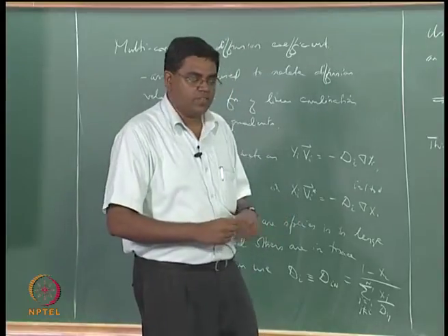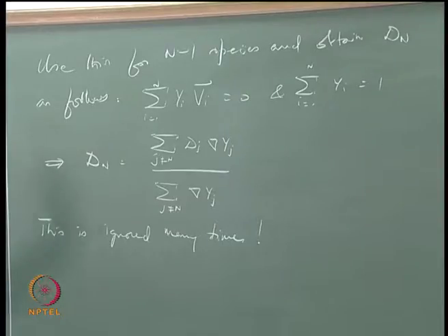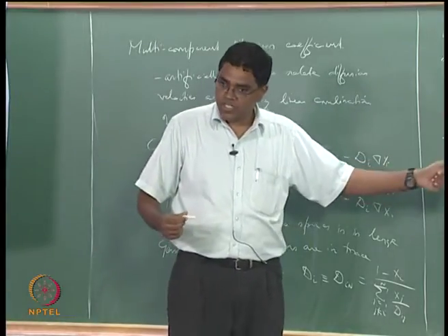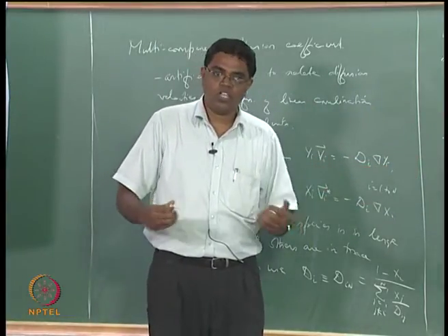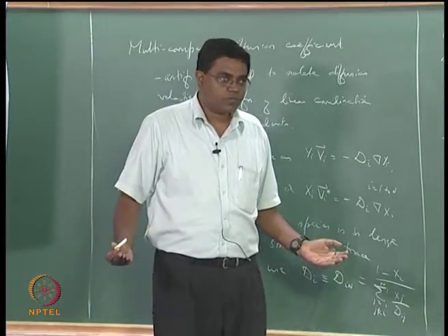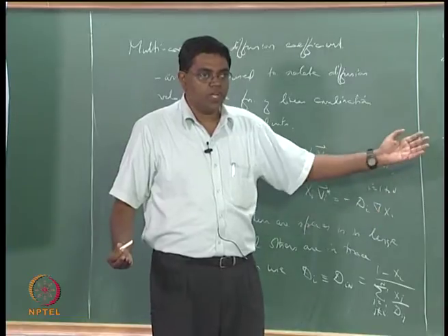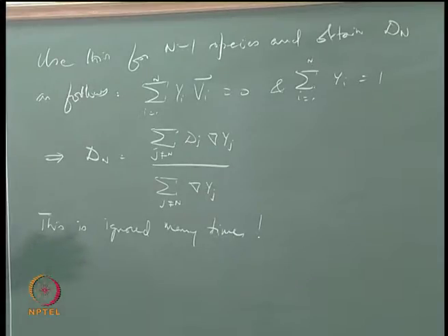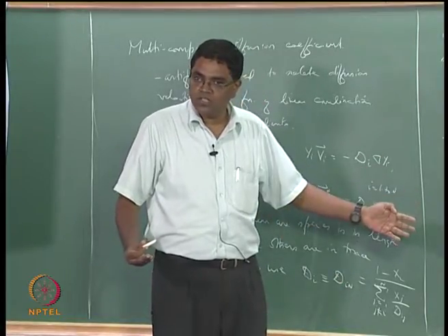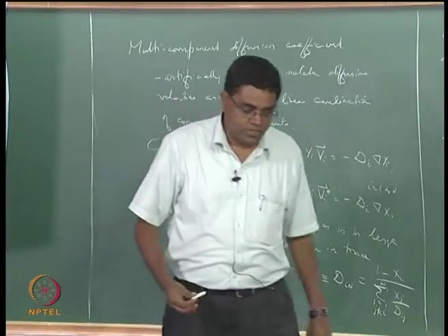In this list so far, of course, wi contains temperature, for which we will have to resort to the energy balance. Then we will find that the momentum equation involves pressure, for which we also have to look at the equation of state. That will completely close the system of equations. So in what we have looked at so far, we have not listed the mixture momentum, mixture energy and mixture equation of state. These three are yet to be done. So let us now do that.